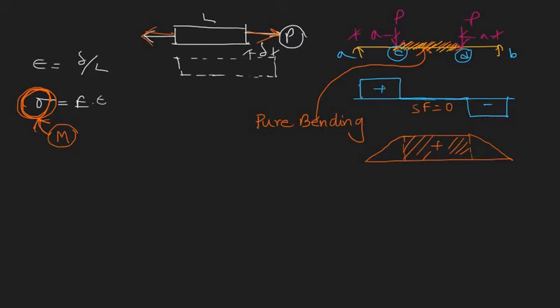So before finding the stress due to this bending moment, we have to make some assumptions, and the very first assumption is plane sections remain plane. Many of you may have heard of this phrase. Well, let me discuss this particular phrase for those who are not familiar. So what does it really mean, plane sections remain plane? The meaning is simple.